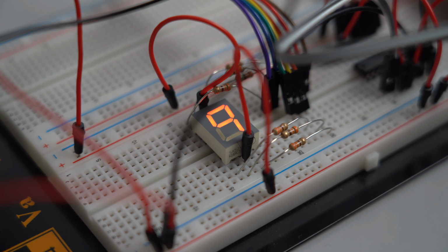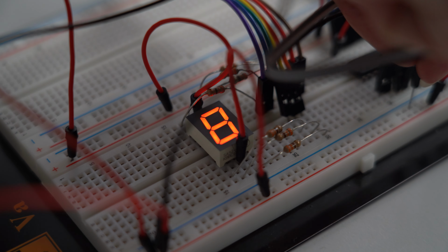You might wonder what happens if you try to use LT and BI/RBO simultaneously to set all outputs both high and low at the same time. This can be fun to investigate yourself. Check the datasheet to make an expectation, and then you can check your expectations in reality.